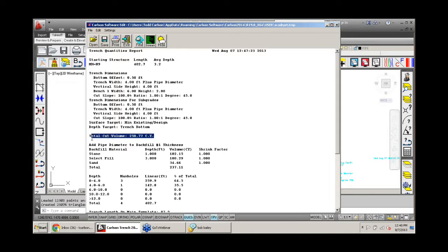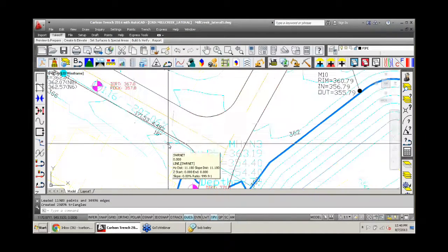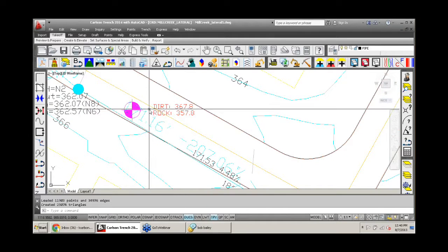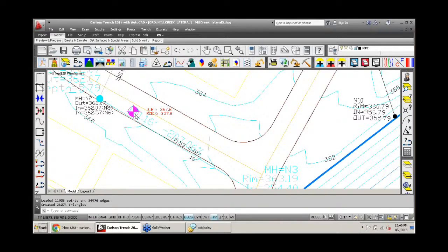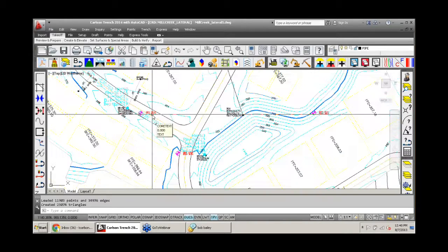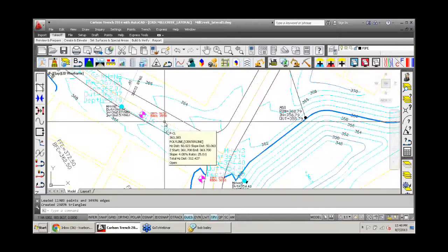Let's look at the cut volumes a little further. So I get the cut volume there, but if I look at this job, I can see that there's boring data on here, and this is kind of the power in our software, in coming from takeoff. The ability to use SiteNet with trench here, and also a Geotech report. And I'm going to put in some borehole information, and it will change my cut volume from just showing a total cut to how much of that is rock.